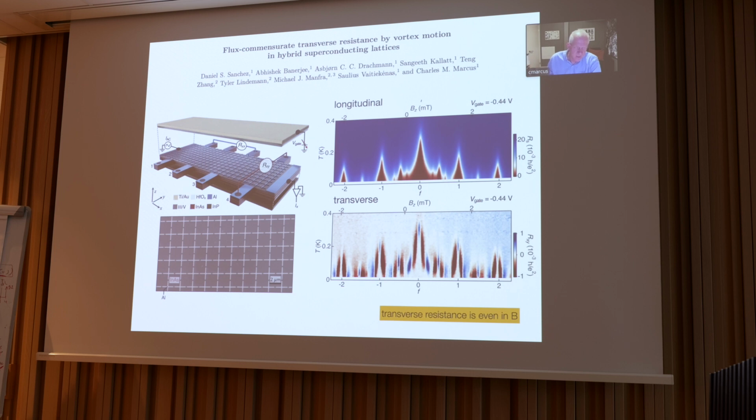But a semiconductor person, every time they make a device to measure the longitudinal resistance, they usually put a few extra arms on to measure the Hall effect because they're usually in the business of measuring density and mobility as a function of gate voltage, and so Hall effect is useful for that.